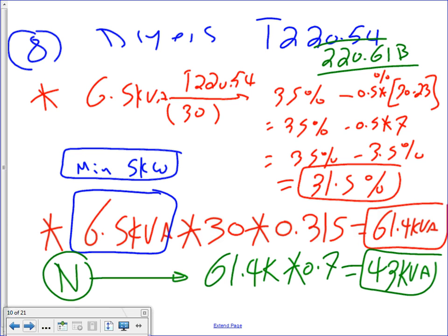220.61(B) for dryers and ranges. For dryers and ranges, it will tell you when you size the feeders, 220.61(B), take them at 70% neutral-wise. Neutral-wise, because they are 240, 120. They have a 120. Typically, the electric dryer runs the motor at 120 and the heating elements at 240. Okay, everybody understand why we did that? And here's your reference, guys. 220.61(B) is the reference for the neutral.